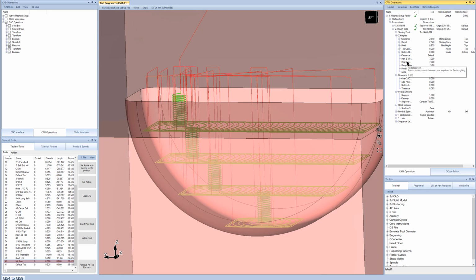The rest step cut is what it would basically do is if the rest step cut is smaller, say if we make this 2, it'll feed down 7 millimeters and mill out this whole area and then go back up by the rest step down amount and just kind of clean up the areas that it couldn't get to, right? So you can experiment with that. This does not work perfectly in every case, so I'd be a little bit careful with rest step down, okay? But it can definitely save a lot of time in some cases.